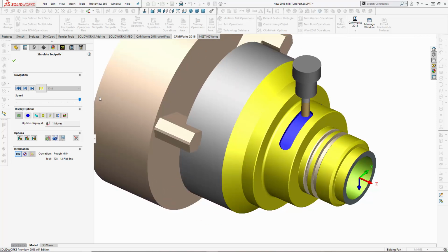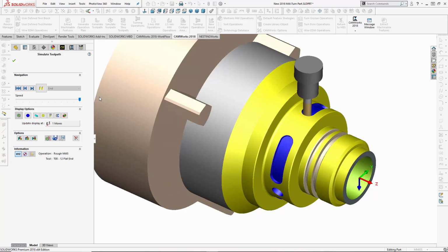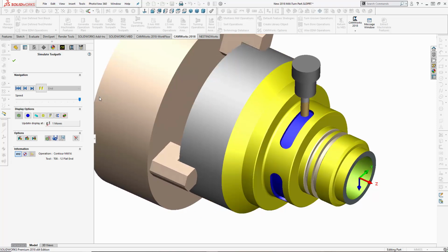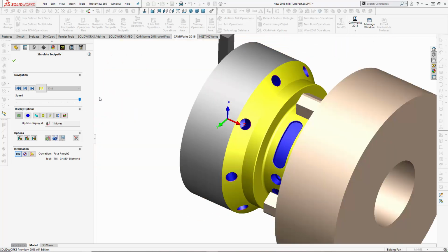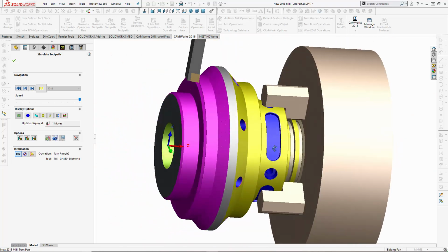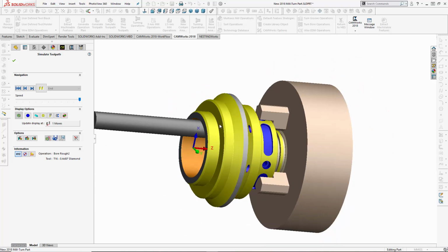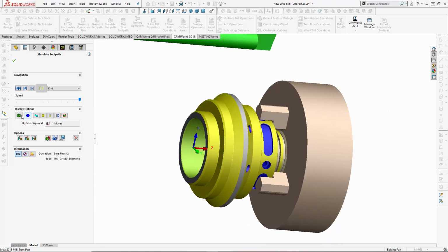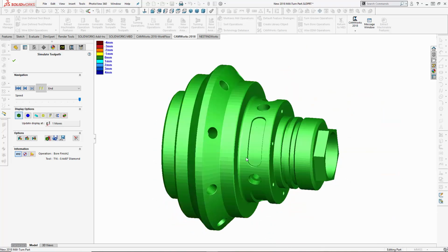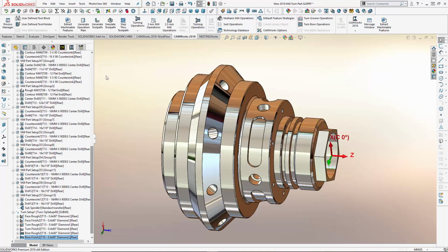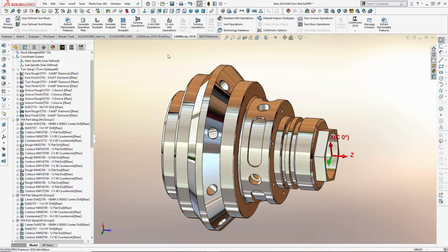of the pockets. Using intelligence-based machining, even complex machining strategies using multiple tools can be stored and reused automatically, saving you time, increasing efficiency, and improving the quality of the finished parts. I'll compare the machined part to the design part again, and now we can see everything colored green, which means the machined model exactly matches the design model, and we're ready to generate G-code for the CNC mill turn center.